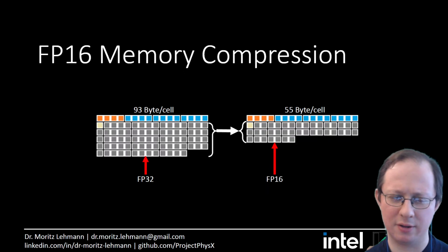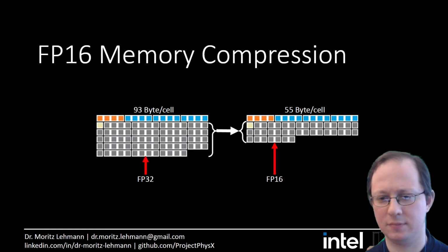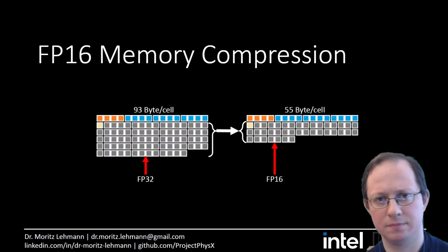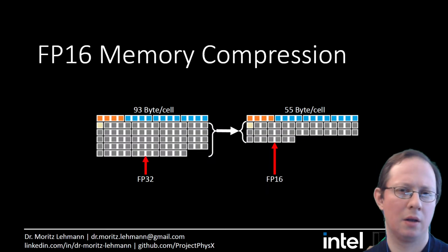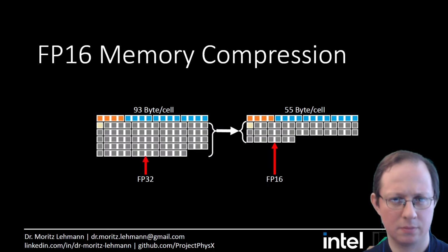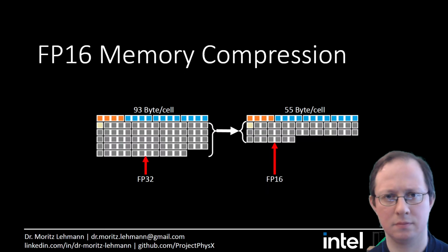It's also in the order of one clock cycle. It's a bit different for different architectures, but the typecasting is very fast. Okay. It's usually done in the data port as part of move operations. The move operations can copy data around in registers, and in the same clock cycle also convert the data type.